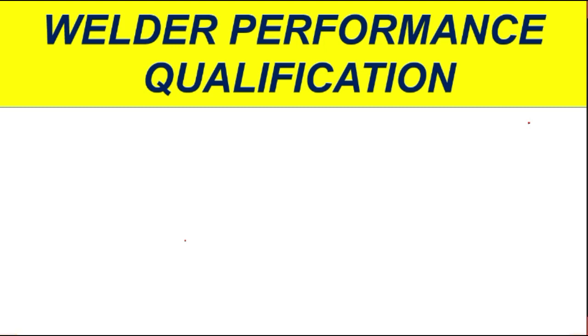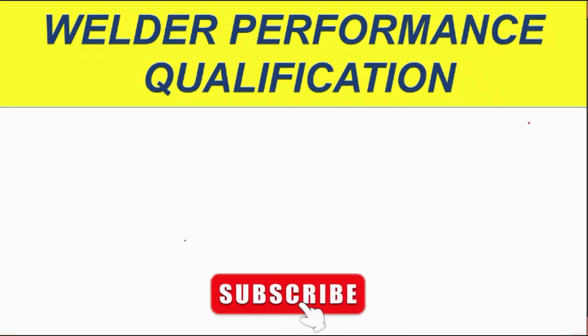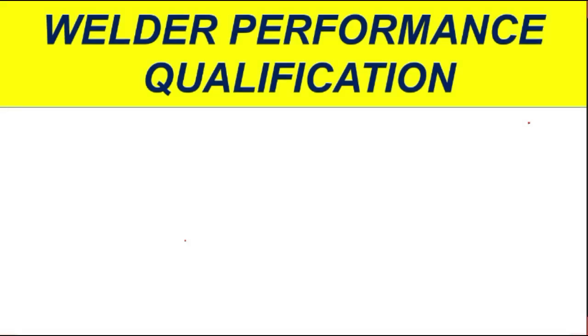So let's start. You know very well that prior to starting welding in any manufacturing or project, there must be an approved WPS. So why are we saying WPS? With the WPS we should know the minimum requirements, then we can go for the welder performance qualification. So what is WPS? Welding procedure specification, and there are many variables: essential, non-essential, and supplementary. Welders must follow those parameters. In welder performance qualification, the welder must follow the essential variables, and if the testing is okay, then they can qualify and do the production welding.